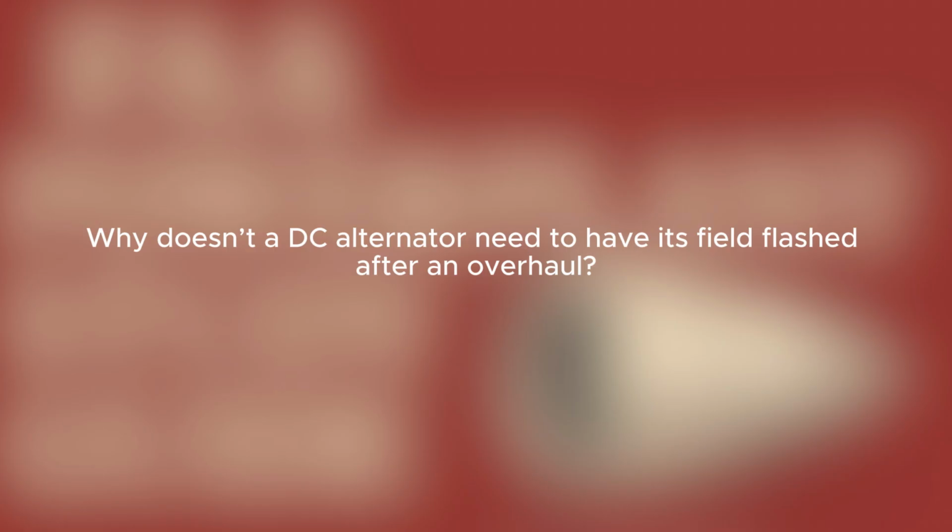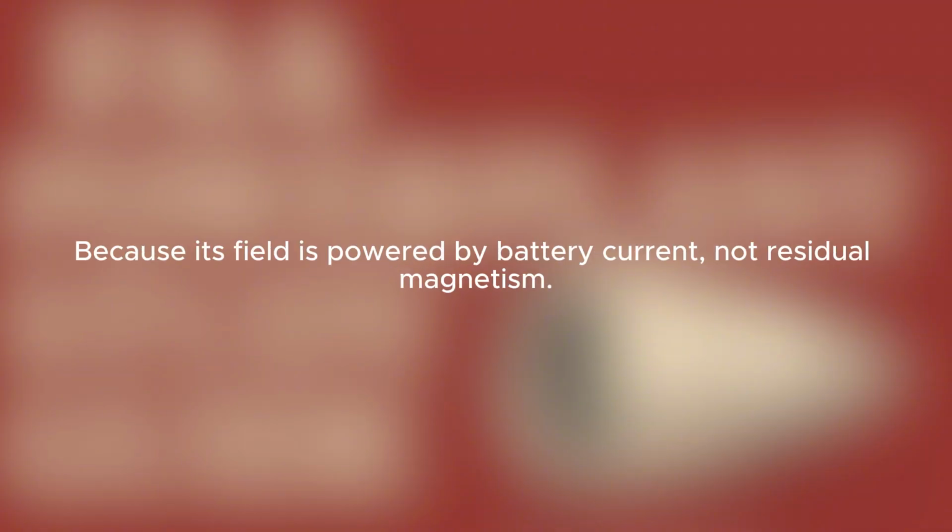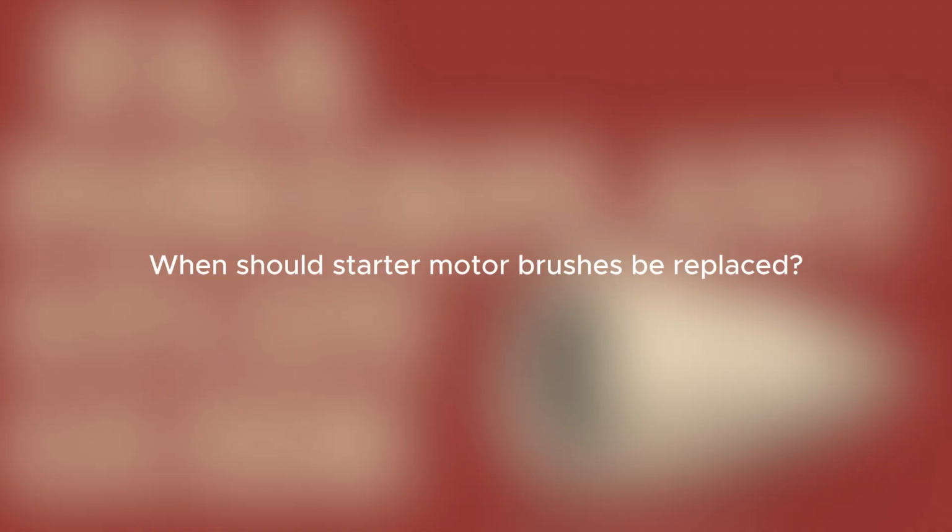Why doesn't a DC alternator need to have its field flashed after an overhaul? Because its field is powered by battery current, not residual magnetism. When should starter motor brushes be replaced? Once they've worn down to half their original length.